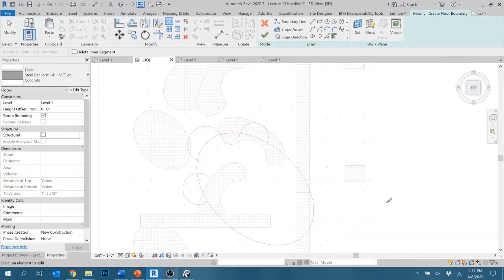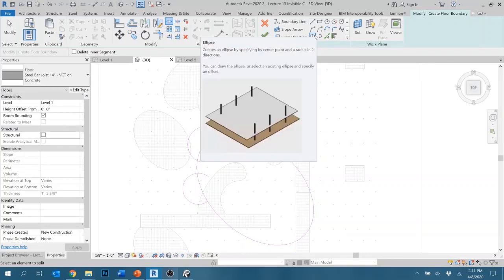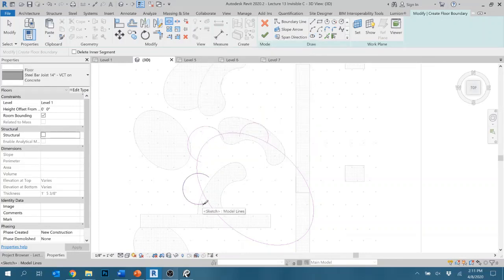If I want to make floors in abnormal shapes, I rely a lot on the slice tool. So let's say I want to do a floor that weaves in and out. I've based my overall large shape on an ellipse, and then I have done 3 arcs.